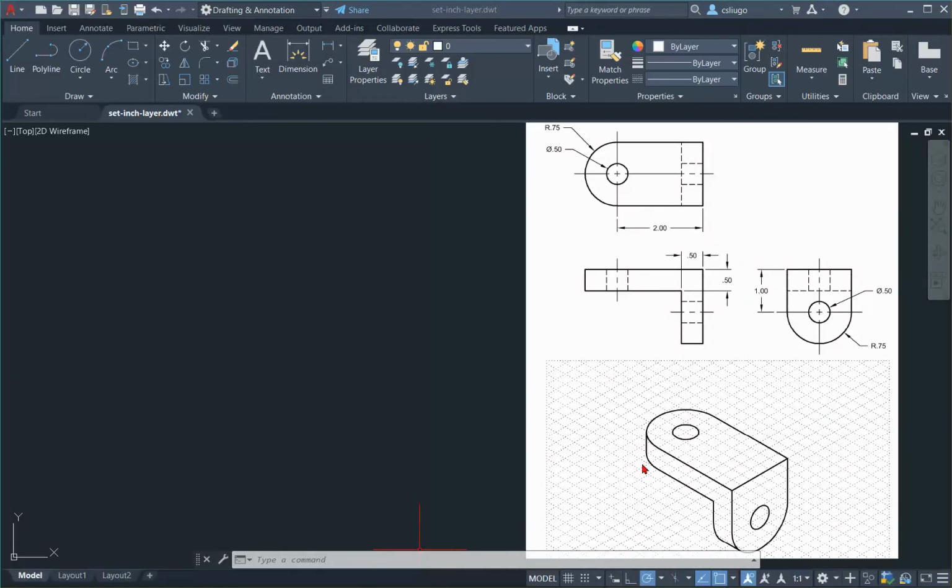Okay, so the first thing you have to do is set your drawing area to a different grid. The normal grid is X and Y, everything goes horizontal and vertical. But you can see this kind of grid is the so-called isometric grid. So we have to change this to the isometric grid. How do we change that?